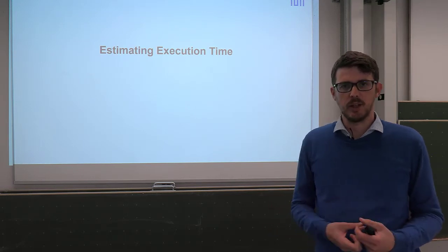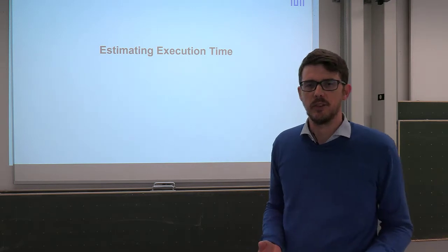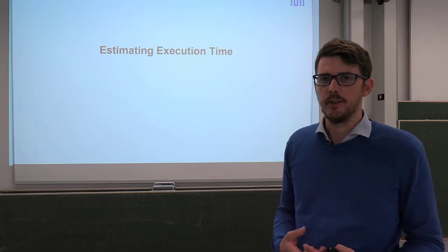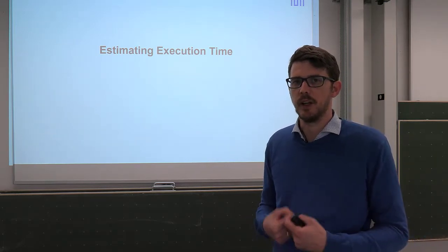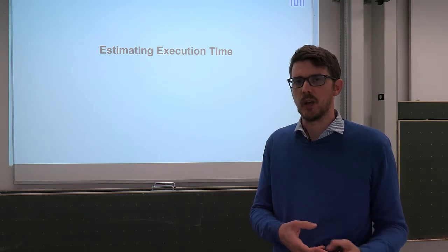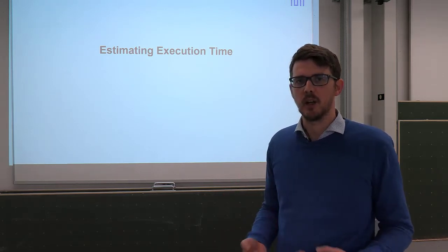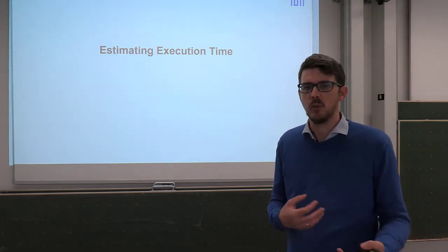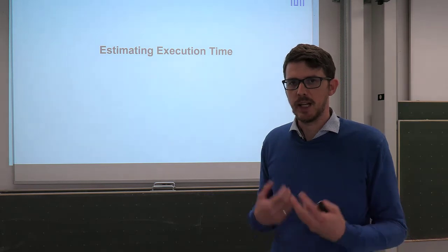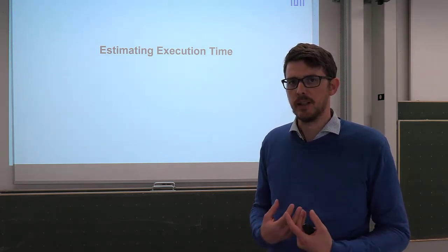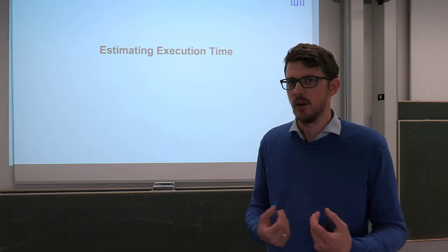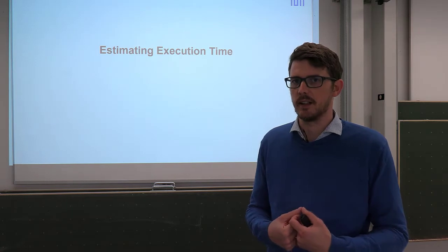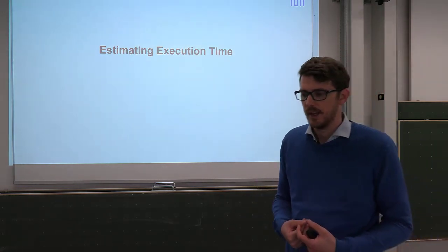And of course, you can use different tools. You can use simulation to find this out. Or another option is that you do kind of a quick estimation. For example, if you just want to find out, should I be using this microcontroller, or should I buy a microcontroller with a bigger core, which has more performance? You can do some quick estimation based on what you know from your application. These quick estimations, of course, are not too accurate, but they indicate whether you're in the right order of magnitude. You know, I want to execute this in 2 milliseconds. Do I reach these 2 milliseconds or not?